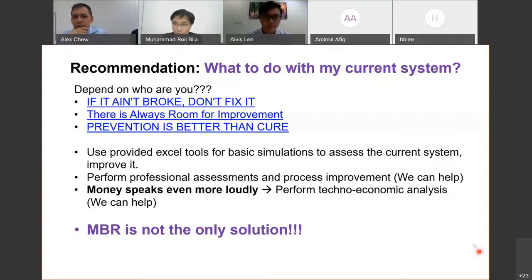Personally, I like your second question. Can we just not do CIP? The answer is yes. But you have to optimize the way you operate the membrane. I'm in favor of running the membrane without cleaning. So if you consult me, can we run MBR without cleaning? The answer is yes. But for the details, we have to discuss in a separate session. Personally, I like to operate the membrane without cleaning, without chemicals, just aeration. It is possible to run that.